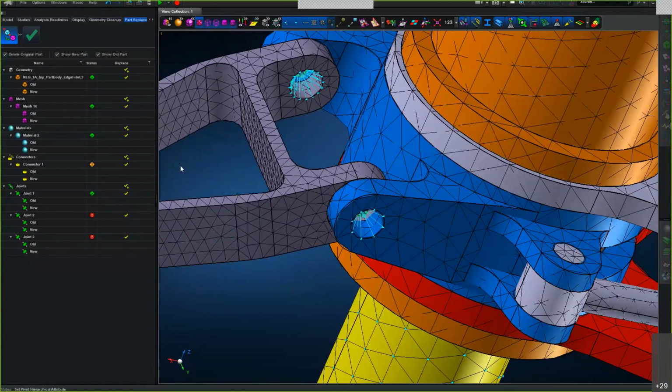Second question is, can the new glue contact tool therefore be used to glue an edge to a surface or to create a lap joint instead of the default two surfaces? So we don't support gluing of beams. It depends what you mean by an edge. If you have an edge of a curve and the curve has got beam elements, that will not be supported. But yes, you can do all of the same gluing operations that you can do with bodies today.